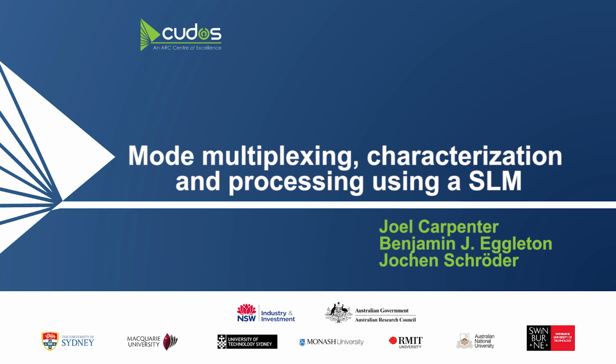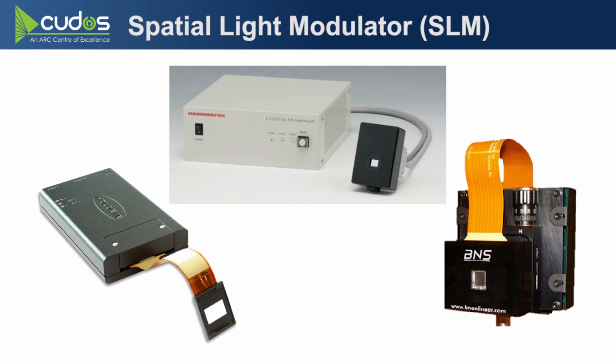This afternoon I'm mostly going to be focusing on using an SLM in the context of MDM R&D as a piece of lab equipment for modally characterizing fibers and components, with particular emphasis on maintaining high modal extinction ratios as you head to the higher order modes. An SLM is great because it allows you to generate and detect arbitrary beams in a reconfigurable way, just in software.